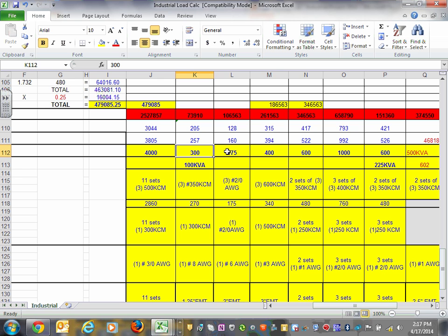That's a good idea. You're looking at a 150 amp panel, upper or lower. Maybe that's a decision that you make. I like to stay, I don't know if you guys stay, within 225 amp panels, receptacle and lights. That's a good rule of thumb when you just throw your panels into the building. So we got these. 300 is close enough.